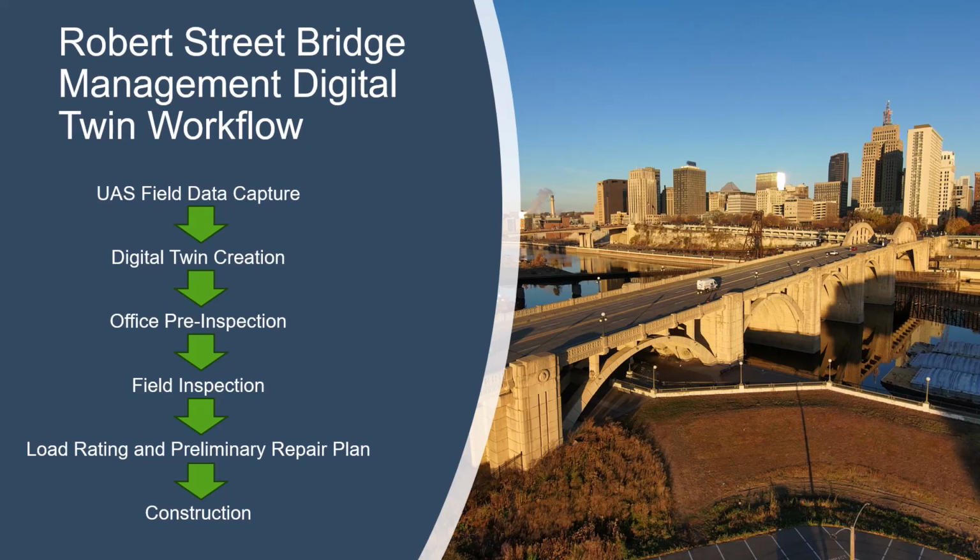So we determined that this was a good option for trying to use this digital workflow, and it did prove to be quite advantageous for us. So the workflow is basically you're going to go out, you're going to capture the data. We did use a drone. The drone took about 3 days to collect the data, and then we did about 1 day before that to set QR codes and ground control points. So not a whole lot of time and effort. It was only a 2-person team out there that had to collect that data.